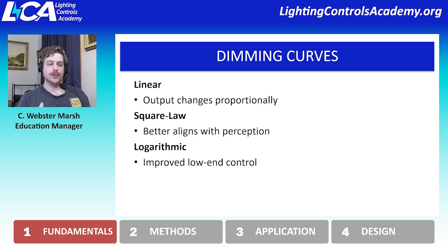And so we'll start going, very slowly, and then it'll start picking up as the fixture gets brighter. And then between 90 and 100% of the dimmer's assignment, you'll see the fixture's actually providing between 80 and 100% of its output. But you don't notice it that much because of the fact that your perception of intensity has altered.